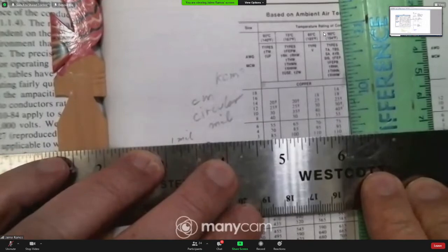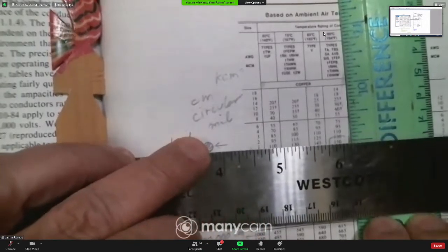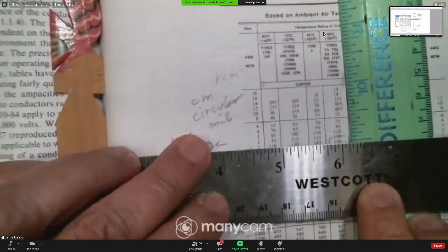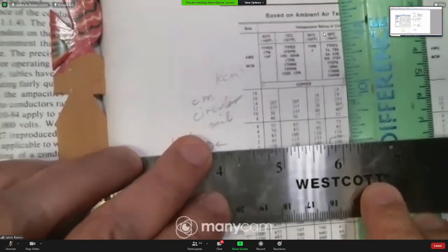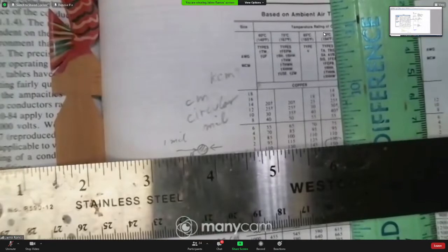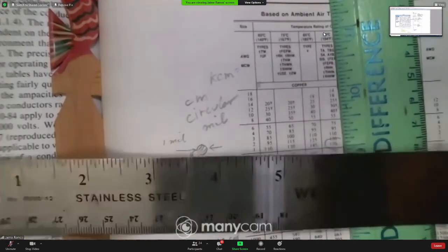Now, we have suggested number 2, which is good for 35 more amps. Why could that be? Because of the voltage drop. It's a long cable. Cable we said is how many feet? 300? Okay, so then the simulation will tell us if we are under the voltage drop or not.